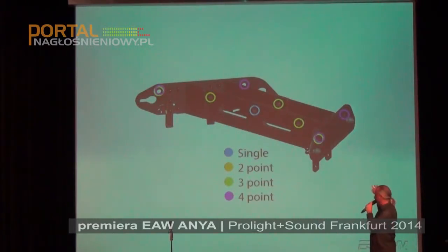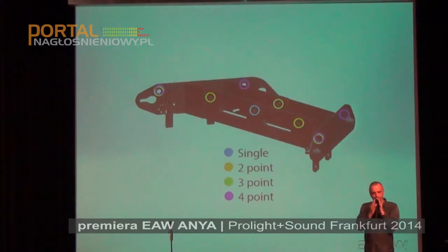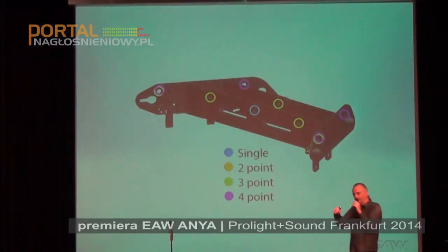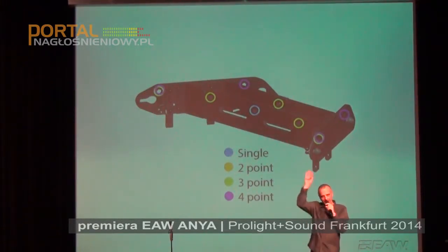Now, also unique is the way the bumpers interlock together. We have a set of bullets on one side, which work on a cam lever. On the other side, you can see that there is a keyhole. So when you put the bumpers together in the stacks, first of all, you're greeted with a lot of play in the assembly. If you have uneven floors, we never wanted you to run into issues putting the bumpers together. So this cam lever, when released, gives you excessive amounts of play to be able to join the bumpers together. When you rotate the cam handle, it draws all of the slack out of the bumpers and pulls them together tight for you to be able to put it up in the air.